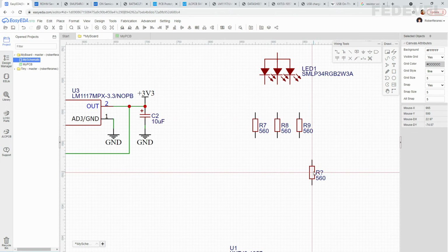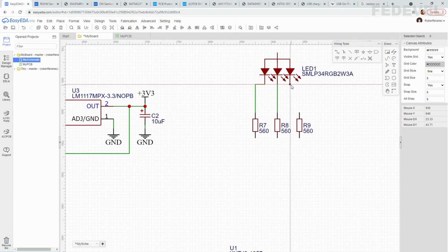and this. Escape. When you would like to connect something in your schematic, you don't have to always use this wiring tool. You can simply click on this pin which is here, and you can just start drawing the line. It is a little bit faster, yeah.